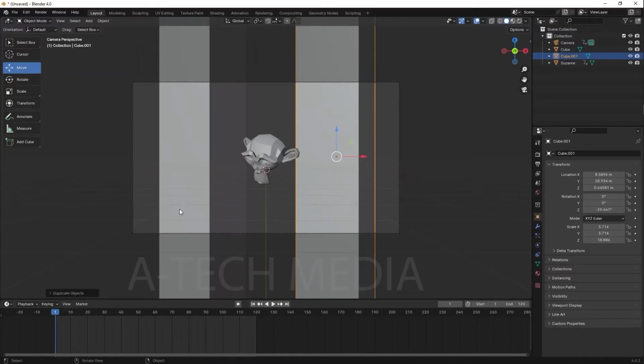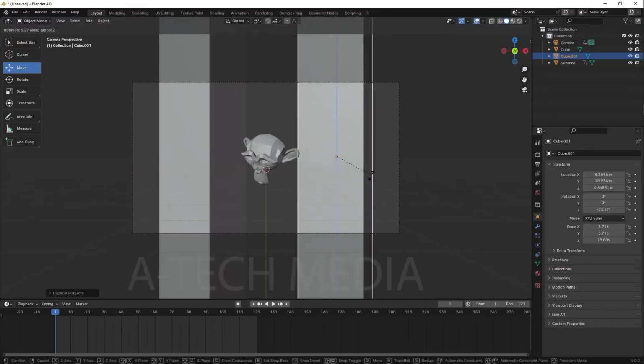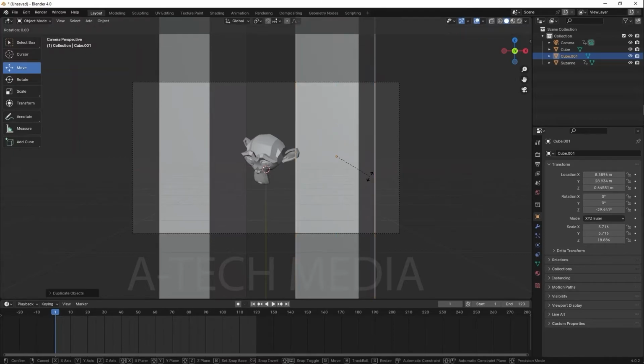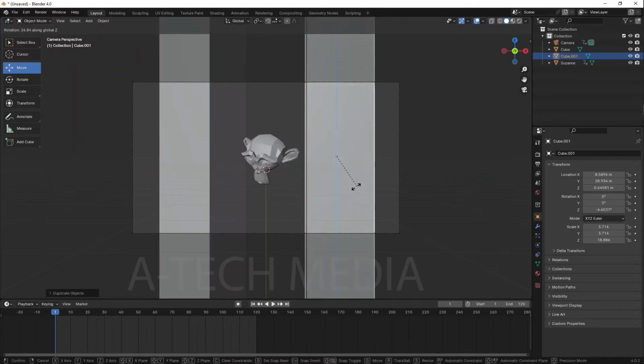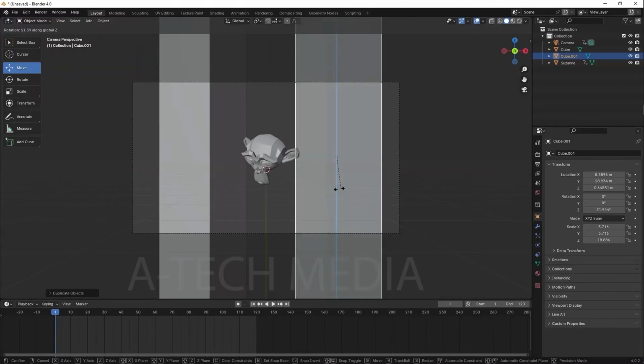It will just snap back to the original location where you had keyframed it earlier. So you have two objects on top of each other. So don't do that, okay? So cool, we have this one here. Maybe rotate it, press R to rotate, Z to constrain the rotation on the Z axis, and rotate it this way, the opposite way.